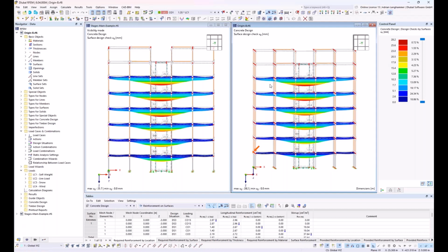Based on a construction stage, and while doing the concrete design, you are now able to calculate the deformation in cracked state, but only for a particular construction stage. So it's the analytical method. For example, in this case you have a final stage, the structure is completed, and then you could calculate the deformation in cracked state.